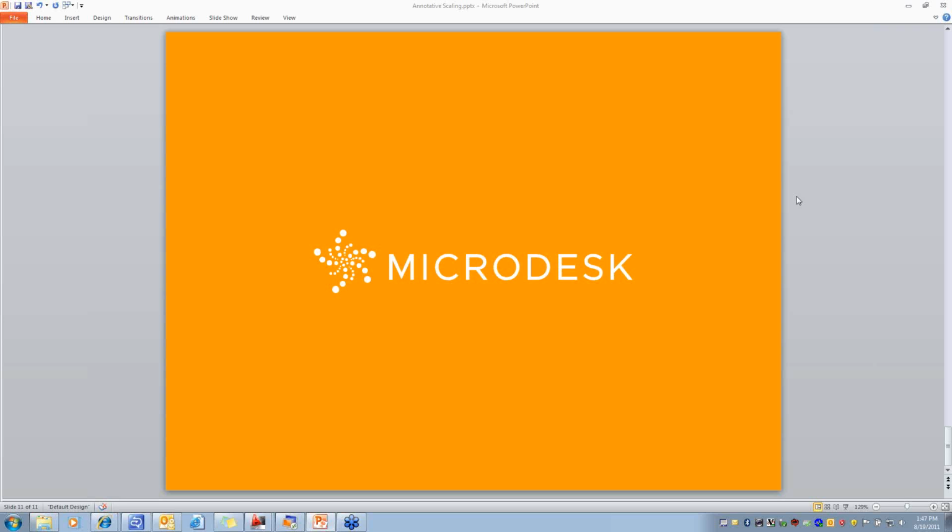Okay, are there any other questions? You can type them in at this point. All right, we do have a couple more coming in. The first question is, does it work the same in blocks, having annotative? Well, you can create your blocks annotatively, and once you create that block annotatively and insert it in your drawing, then yes, you are doing the same thing where you're going to see that field in the properties and be able to go into the annotative object scale and assign different scales to that block.